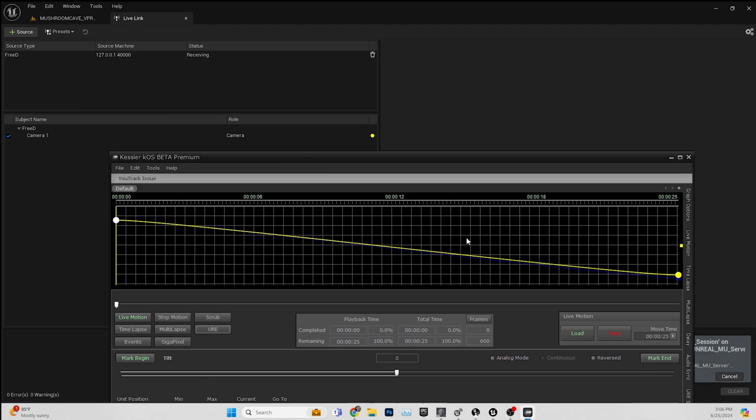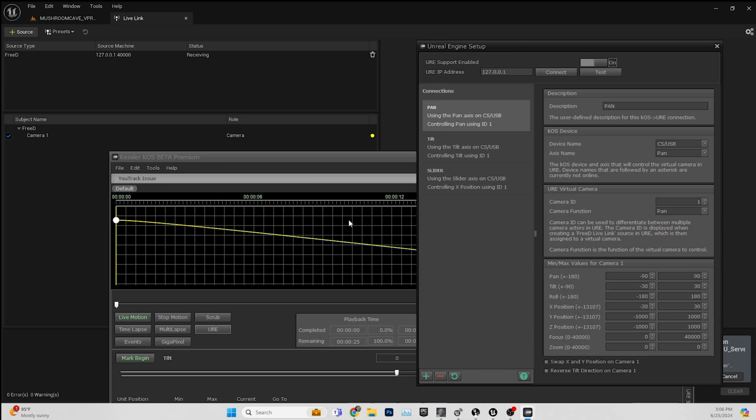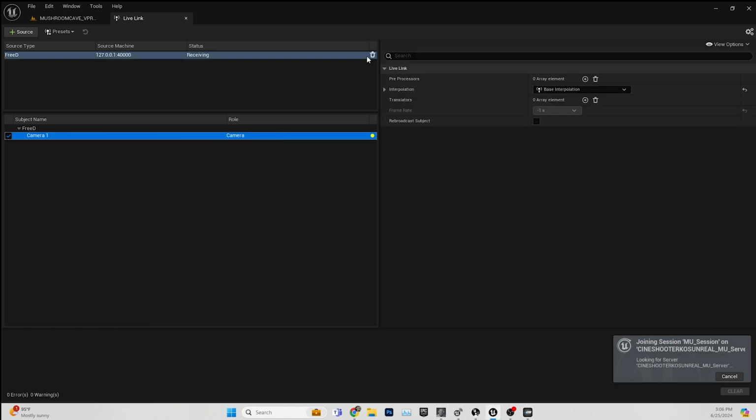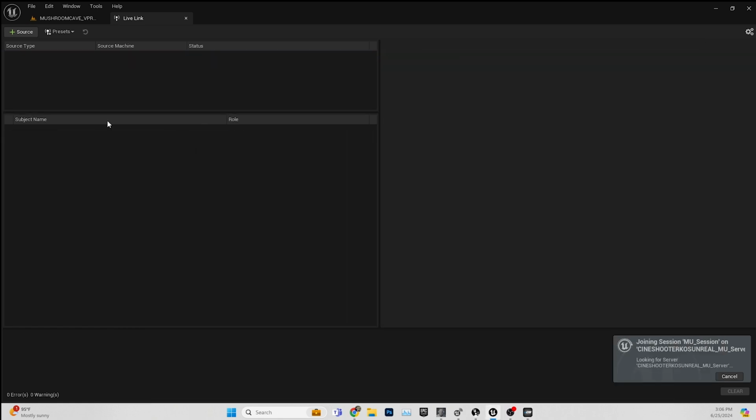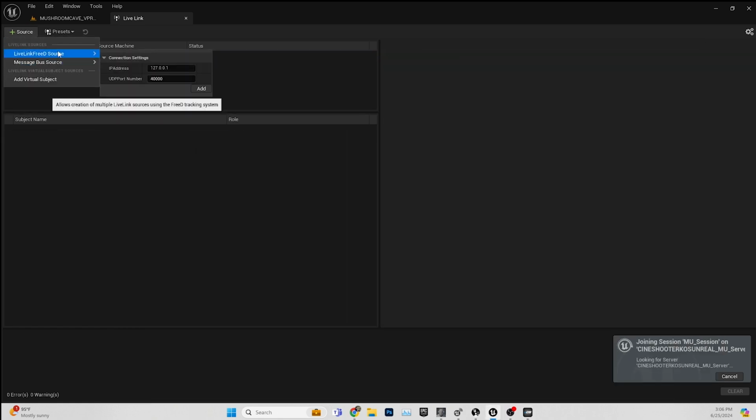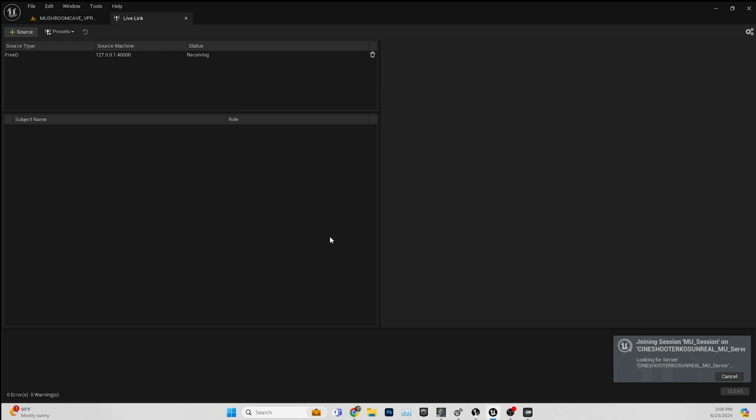Okay, so when you connect to Unreal, in fact, let's go ahead and just trash this all together. We're going to start this brand new. We're going to do a new 3D Live Link source and add, and then that's it. That's all we need to do there. Listening to itself. If it's coming in from a different location, you'll need to put that in there. But if it's all on the same machine, it'll be just like this.